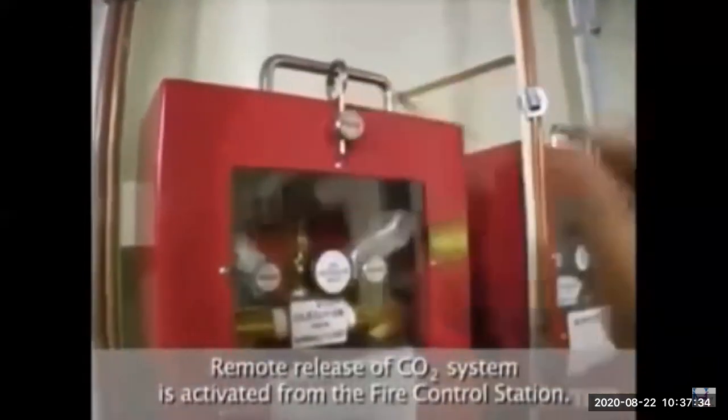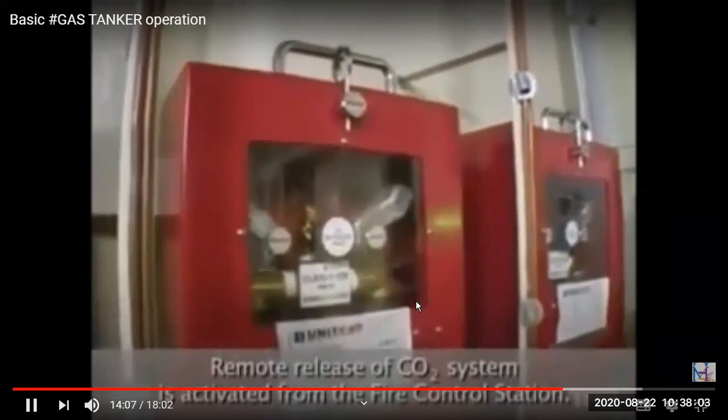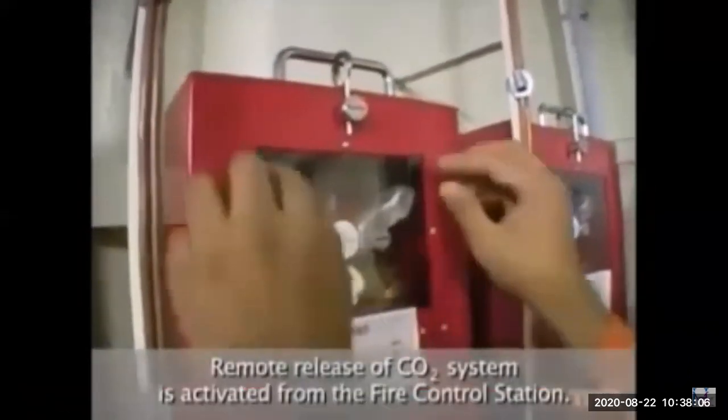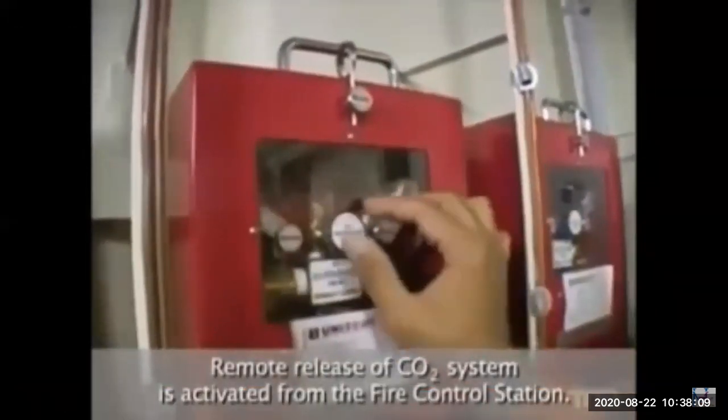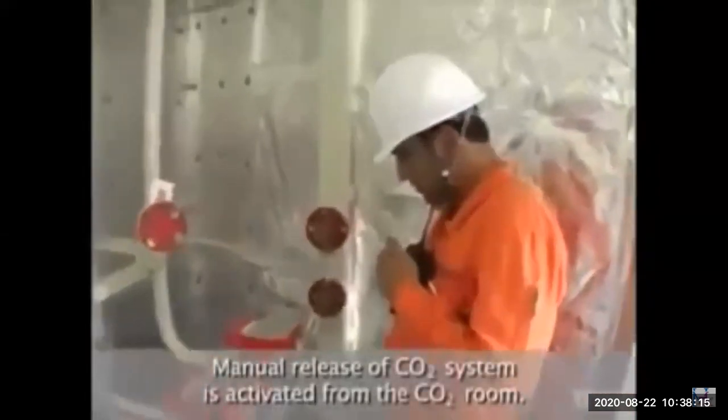Take out the pin, but be careful before opening the valve. First thing is that all persons should be out, and many times if you open this pin, it's connected to some purifier room valves, and your fuel oil to many of the pumps can be stopped, depending on the ship. So be careful. Never open this valve just to check the bottle. So you open the pin, open the box, and then rotate and open the pilot bottles. Put the pins inside and lock down, and open the pilot bottle, and the CO2 room bottles will be activated.